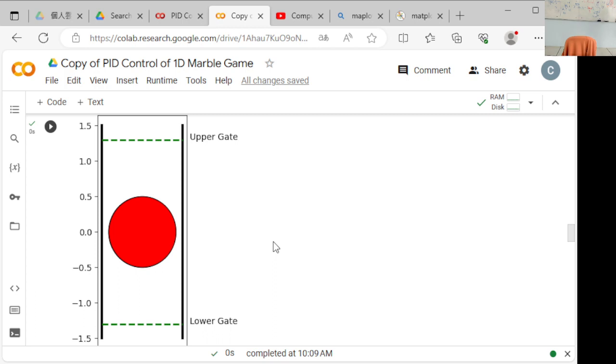Similarly to this car driving control here, I had a tough time convincing the students that you cannot just implement, if you're to the right of the line, turn left, if you're to the left of the line, turn right, because what will happen to the car is that you will also end up with unbounded oscillation.